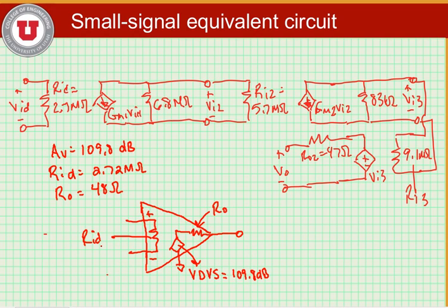Alright, so that's how we do the analysis for the 741. And you can do similar analysis for almost any operational amplifier. We start with the DC bias, and then we do the small signal analysis. And the only difference in doing these complex amplifiers is recognizing which transistors are acting as DC biases and which transistors are acting as small signal gains.